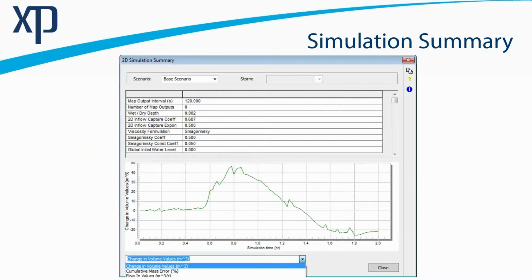The XV2D engine is an implicit solution, which means it uses matrices, and therefore it does rely on convergence to provide a good solution. It's fast and uses big time steps, but you do rely on that convergence to be a measure of how healthy your model is.